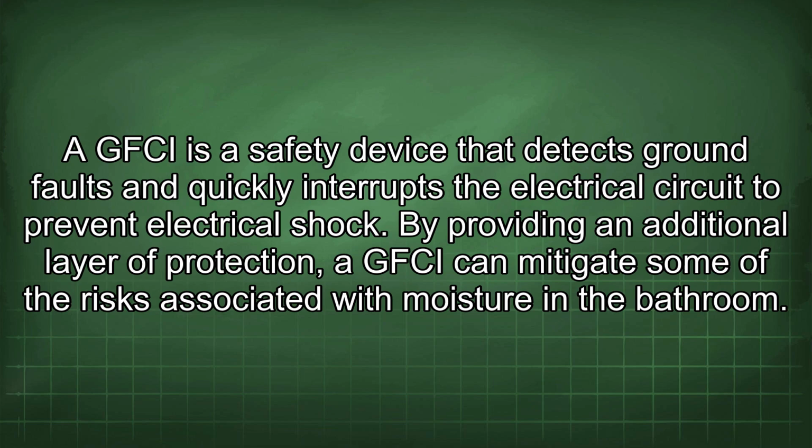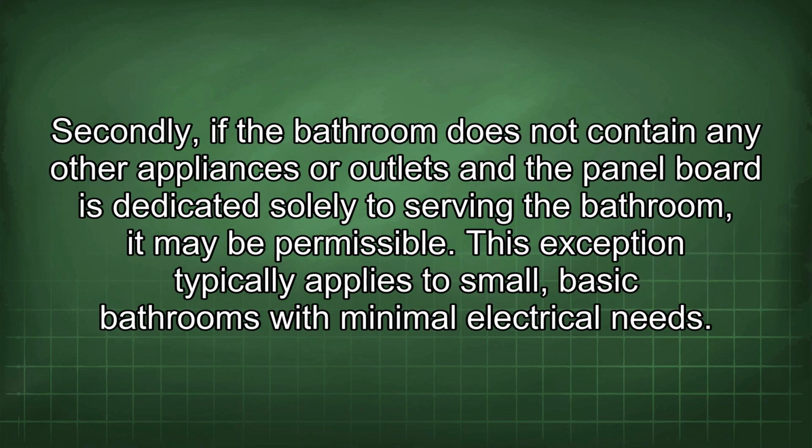By providing an additional layer of protection, a GFCI can mitigate some of the risks associated with moisture in the bathroom. Secondly, if the bathroom does not contain any other appliances or outlets and the panel board is dedicated solely to serving the bathroom, it may be permissible. This exception typically applies to small, basic bathrooms with minimal electrical needs.